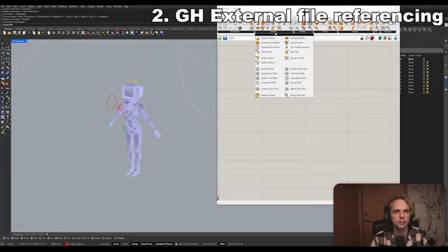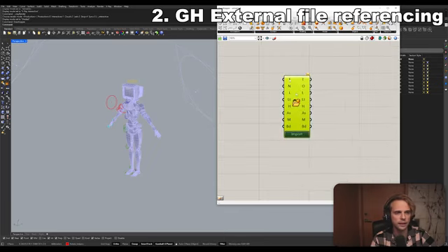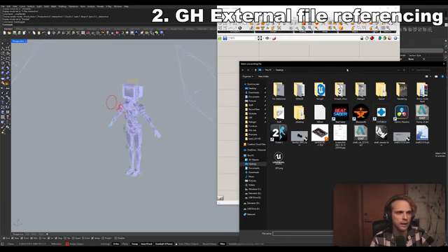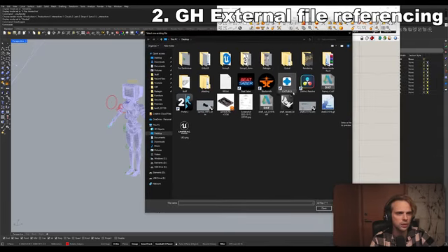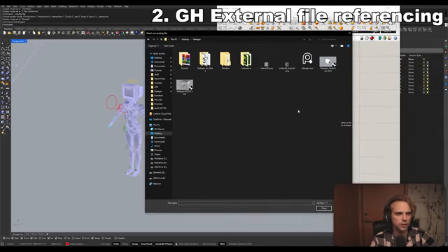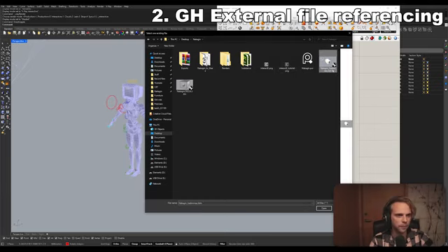Now, Grasshopper is able to import external files into itself, read external Rhino files. You could have done that before with certain plugins, but now you can do that just with Grasshopper itself. So if I choose the import content node right here, it asks me for a file path. I can right click, set one existing file, and I can just navigate to, we did the Nakagin Capsule Tower project recently. Let's open that one up. So Nakagin, get the minus, hit open.